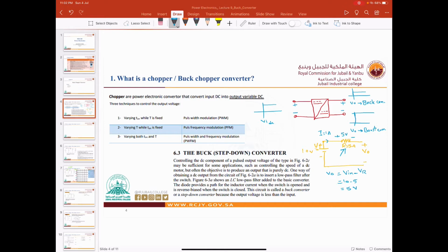This is for a small circuit. If we have a bigger circuit, then the losses are very huge, right? That's why we do not prefer using the old-fashioned circuit here. So we will use something called a power MOSFET. We will use the chopper by doing the PWM.